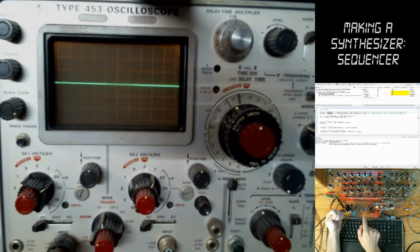At some point, when you increase that feedback so much, you have the output of the filter going back in the filter and being so strong that the filter is just being overpowered by this continued feedback. And then at some point, it's so overpowering that anything that goes into the filter is immediately drowned out. And the output of the filter, what you're feeding back into it, has enough energy that it keeps going through the filter over and over and over.